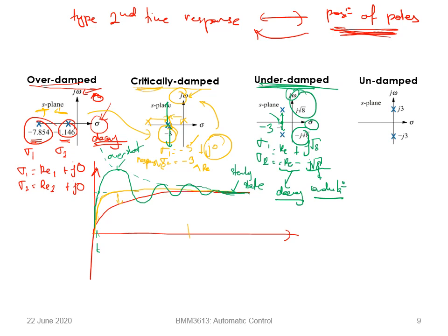So now what can we do next? We have tried three variations of position of poles. At first it was different but real. We took it closer to become real but at the same point, and then it's not just real, it also has real and complex components. So next, let me change color now. What we can do next is try to move these two points closer to the j omega axis, or sigma equals 0. So previously it was in underdamped, it was here.